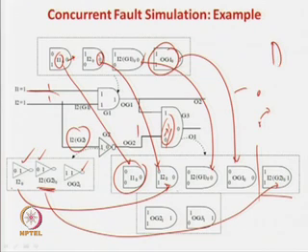In this case the signal changes are from 1 to 0 and from 0 to 1. So, both signal changes are there. This gate can be brought in from this list as well as from this list. Anyway, this gate is already added. So, this gate is changing the value to 1 here, 0 to 1. So, this gate's impact we are bringing out over here, and O2 G1, that is this one, this net you can think of as the O2 output to this net stuck at 1.